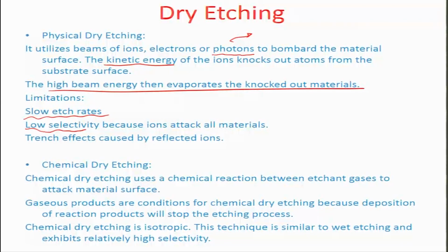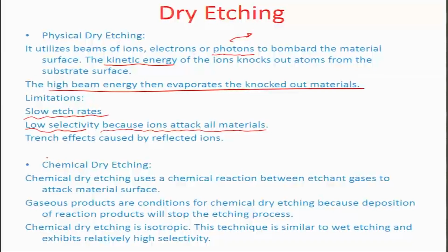But here in this case, because of the ion attack and the rebounding of the ions, generally whatever is being attacked by the ion would have some kind of a thermal energy and melting or vaporizing aspect. So, there is not much selectivity unless there is a masking or shielding which is offered through a shadow mask, which I will come to later probably when we talk about lithography processes. So, there are these rebounded ions, or electrons maybe, which are able to etch the surface, but not probably to that level of roughness.